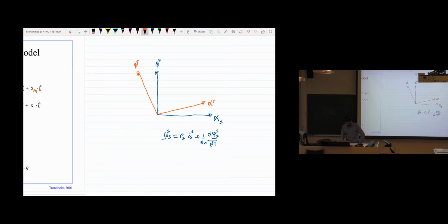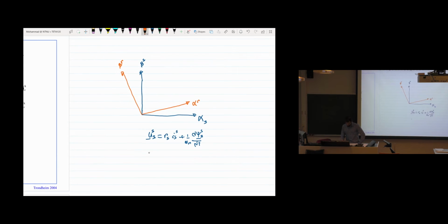And also we check the rotor voltage, and we saw it, UR in the rotor frame, and then we have RR, IR plus 1 over omega n d psi r dt. I put their space vector here, or they are in phasor or vector. So this is what we see, and we also see that there's an angle between these two, and we're saying that this is theta.